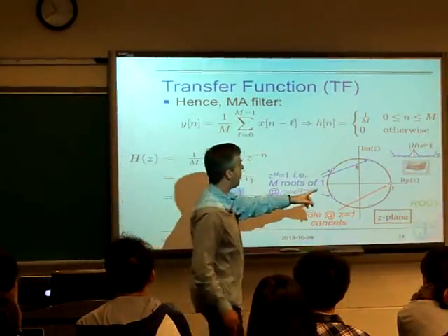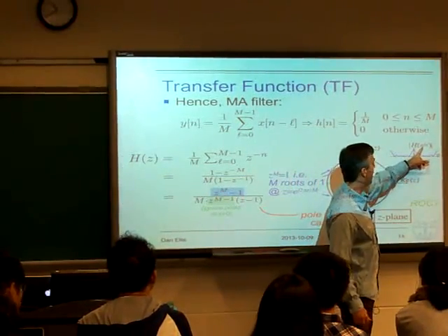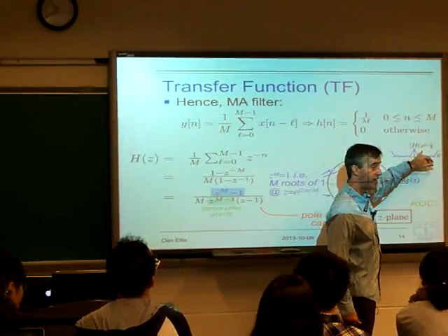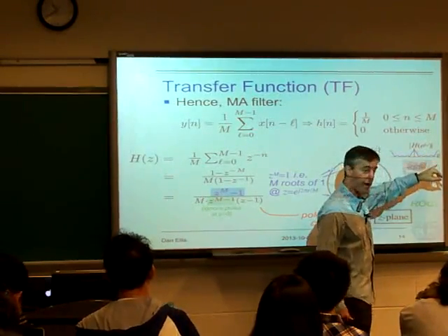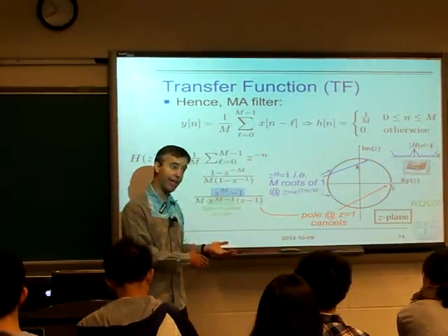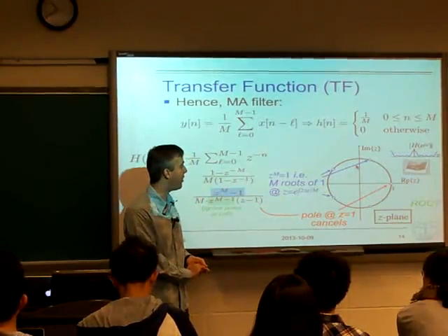And so when we actually plot that, when we unwrap that red line, we get this, the magnitude of h of e to the j omega. That's what it means, magnitude of h of z for z equal e to the j omega, which we recognize as the magnitude response of this moving average filter, the thing we calculated a few slides back when we were slicing it at 0.1 pi and 0.5 pi.